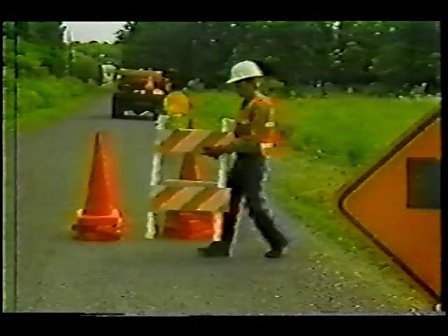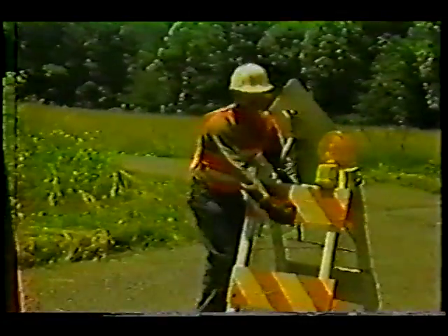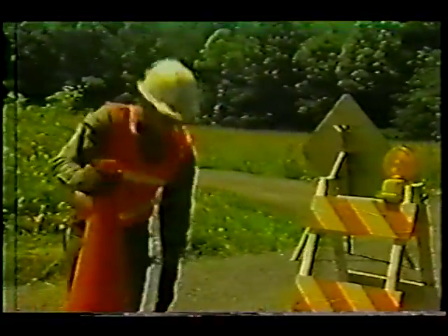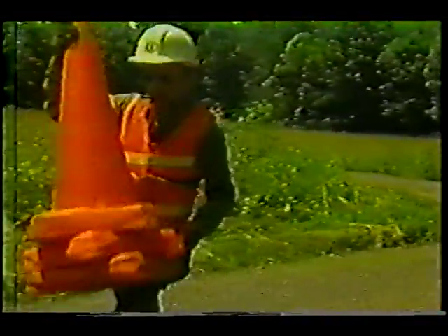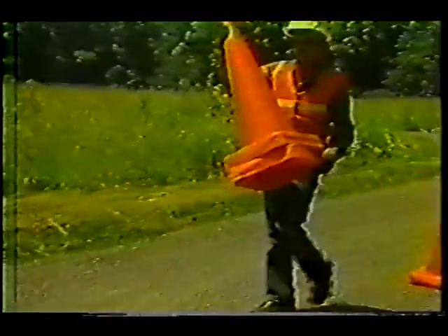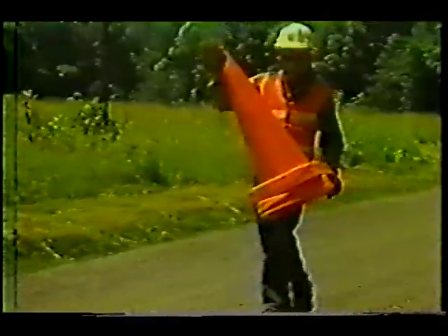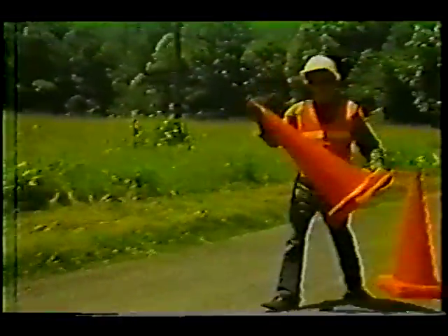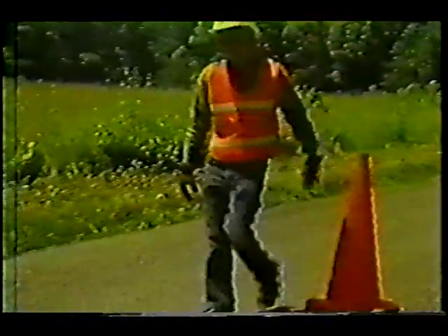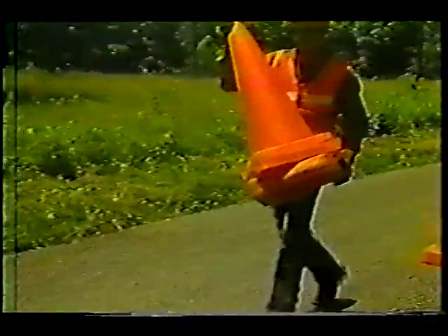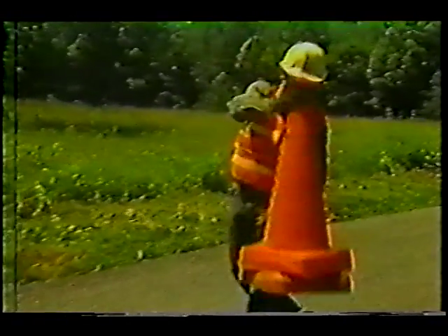Now that we have briefly covered the 8 steps, we will look at each step in detail. Step 1. Place the traffic control devices at the work site. Proper placement of these signs, cones, and barricades is important to the safety of your crew and the passing vehicles. Place these devices so that drivers have adequate time to respond. For further information, refer to the IRF videotape, Traffic Control During Maintenance.